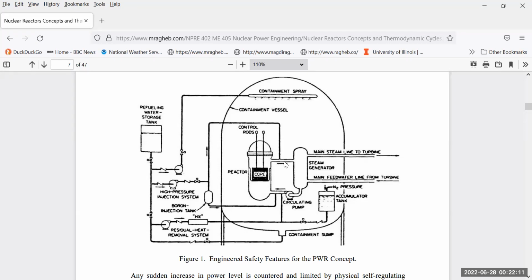If an earthquake happens, that would prevent your core from being cooled. And if you don't cool the core, extract the energy release from the fission process or from the decay heat process, your core will melt. So the loss of coolant associated with an earthquake would mean that the pressure in the system would be decreased. And the sensors will sense that, and immediately, if the pressure decreases below 20 atmospheres, we have what is called the accumulator tanks. Under nitrogen pressure, the water is automatically injected into the system to cool it.